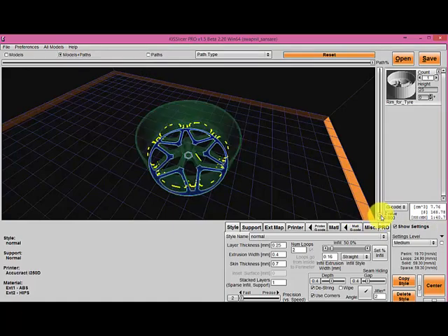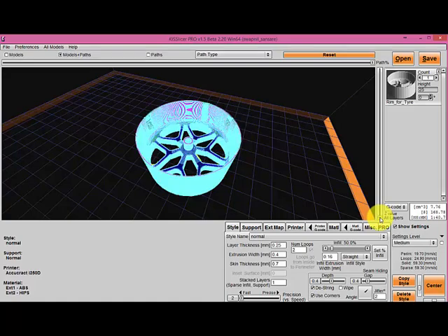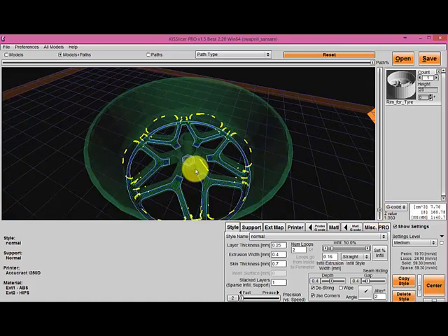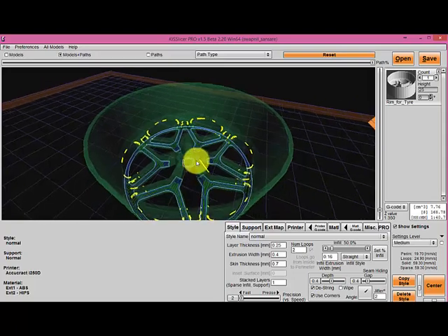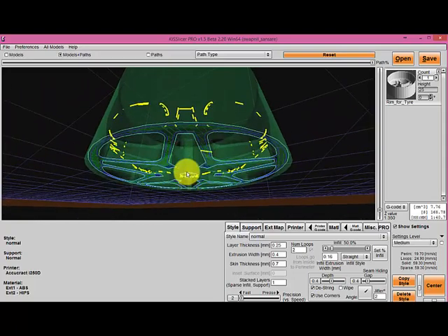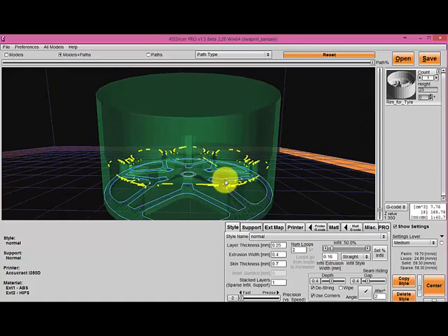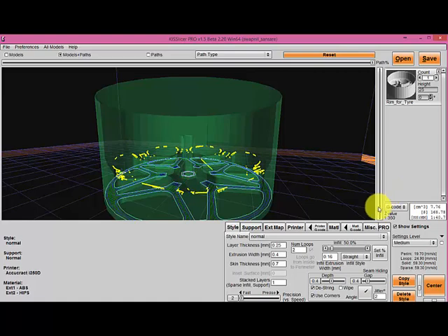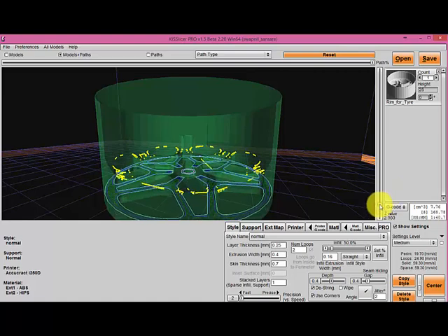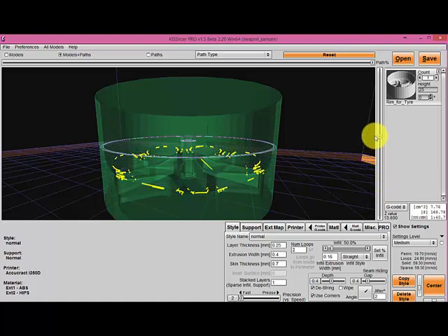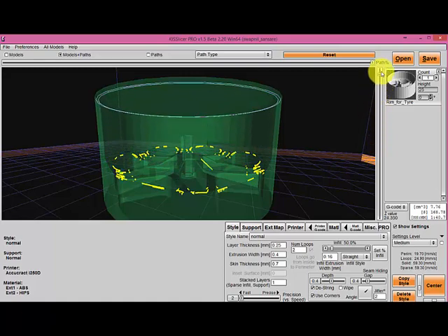On the right hand side there is a scroller, so you just scroll from the bottom layer to the topmost layer. When you start from the bottom side, you can see the print happens, but the center part is being printed simultaneously and there is no support from the ground. That means this would be printed in air, and that will not give accurate results because that would be hanging material and would cause distortion in the print model. The rest of the layers come out good because they go layer by layer and are supported by the bottom geometry.